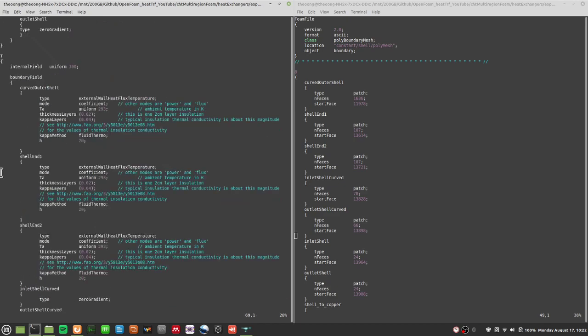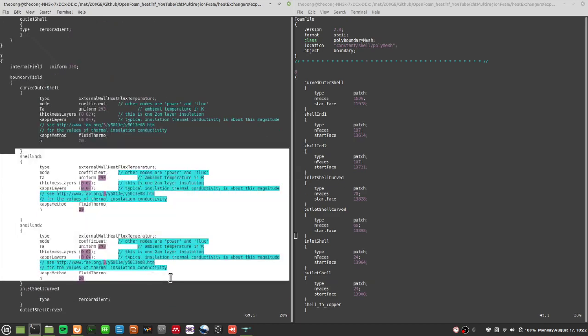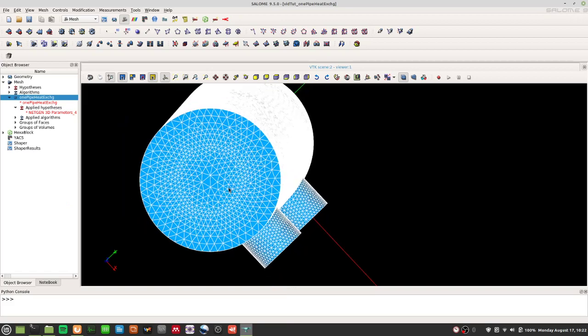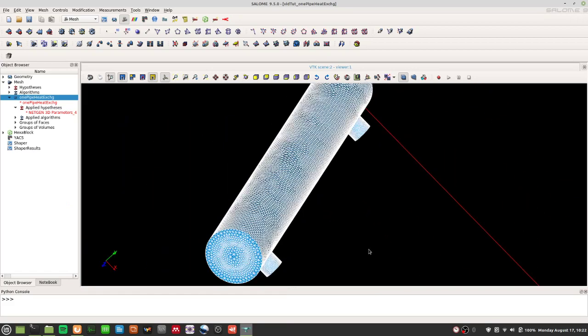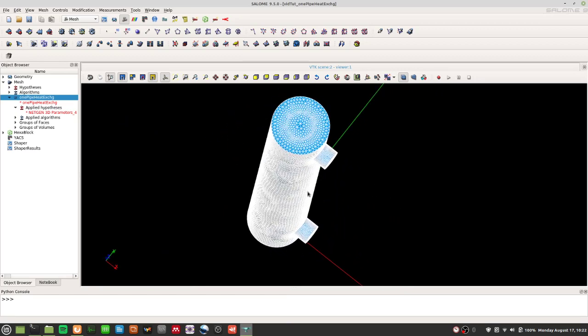But these parts are, let's say, in your heat exchanger. Okay, this is a more fine mesh of that heat exchanger. You might have parasitic heat loss because these parts of the heat exchanger are actually exposed to air. Of course, you try and cover it with some insulation, but by and large, they will be exposed and you will lose some heat to the environment, or gain some heat, excuse me.